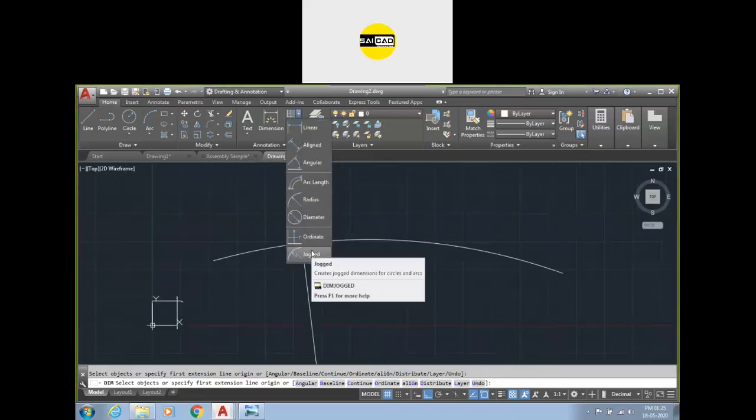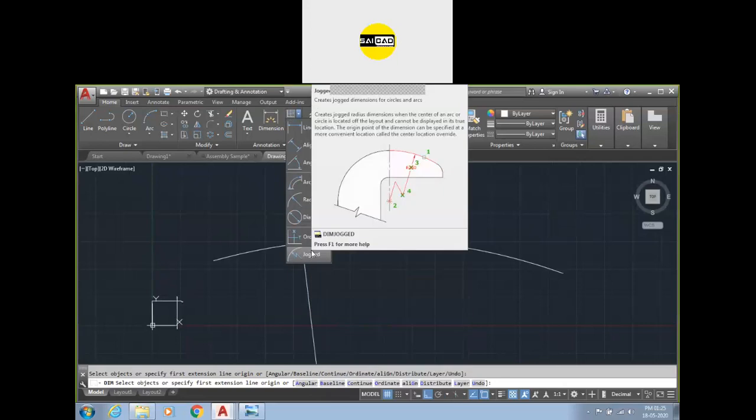You can see in the example here, you can read that jog dimension creates jog radius dimension when the center of the arc or circle is located off the layout. Like we have in this drawing, we have the center of the arc off the layout or off the window. We can just create a new center to represent the dimension.